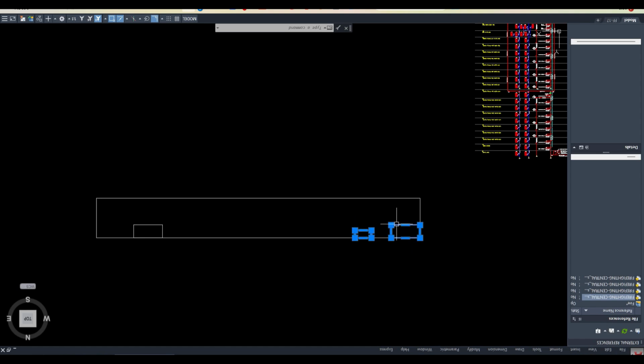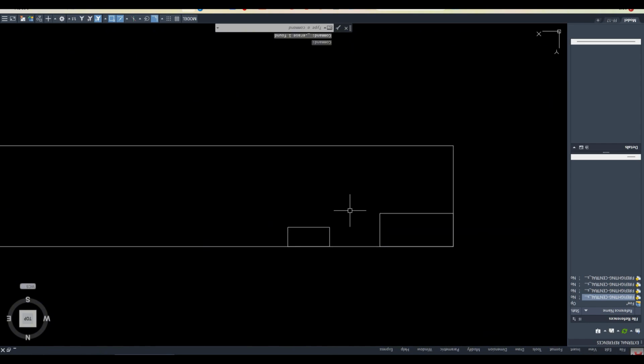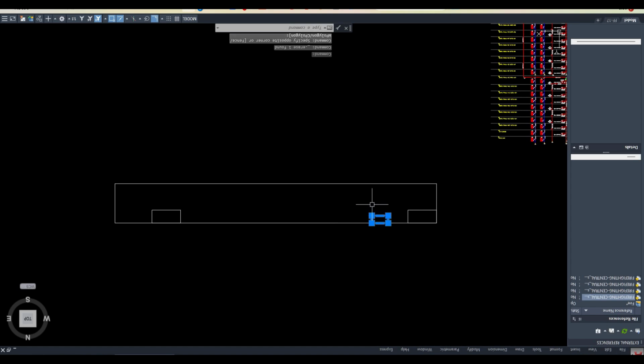So this measurement you will always take from the door. Okay, so let's say the door is here. If the door is this side, then you have to measure it from the door from here. Then from here, if you start running your hose reel, it will maximum reach 30 meter, which will cover the 10 meter this and the 30 meter that, 40 meters.